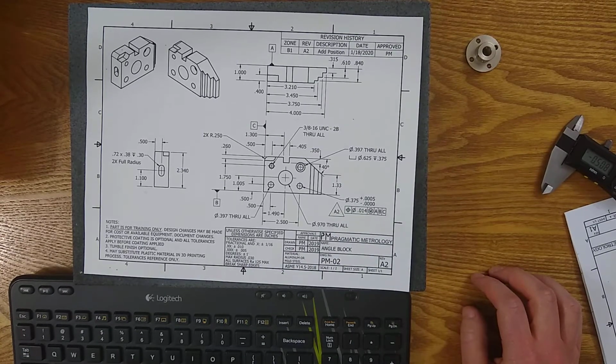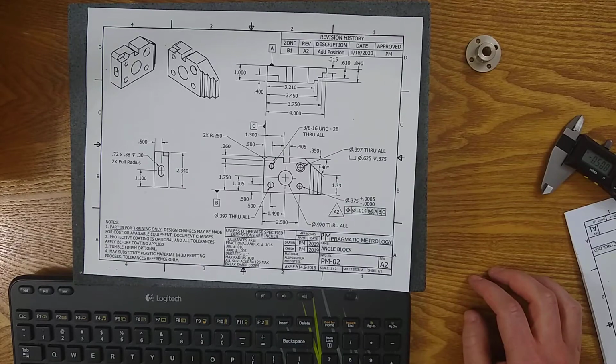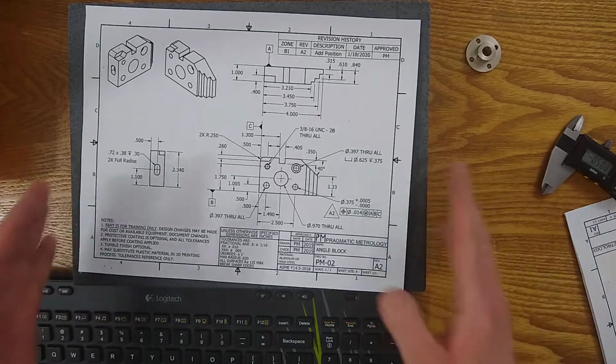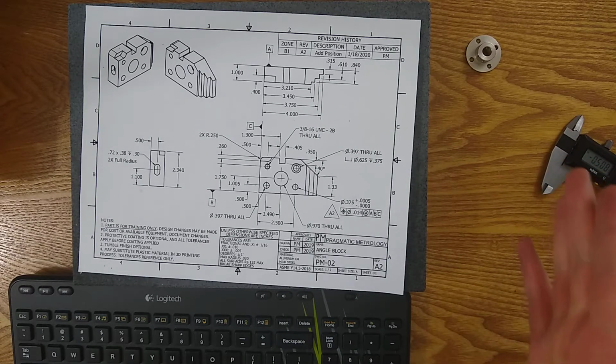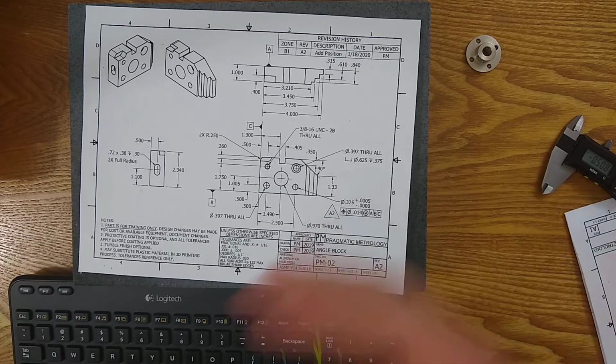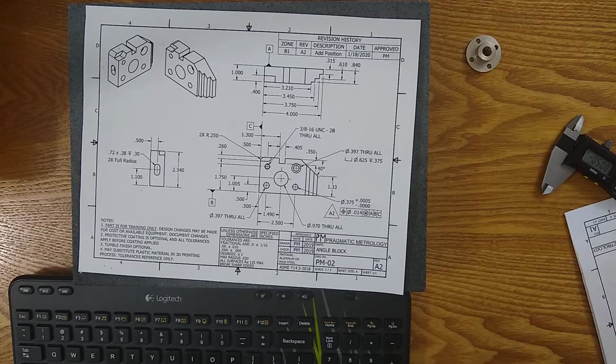All right, we're almost at the end. Implied form error. This is pretty much what I just tried to draw. As I mentioned, these are some of the GD&T symbols for straightness, flatness, circularity, and cylindricity. When you see these, there actually is a very strict GD&T requirement. But when you don't see these, that type of requirement still exists.